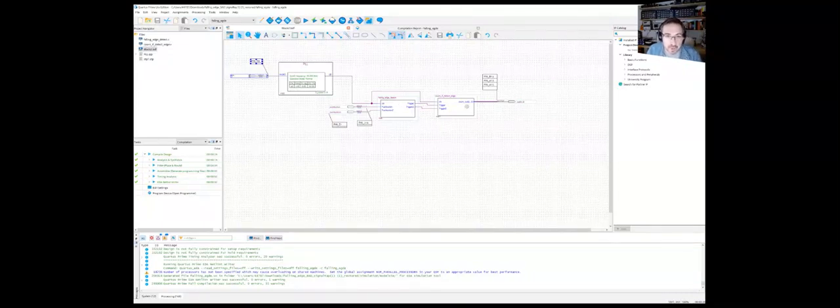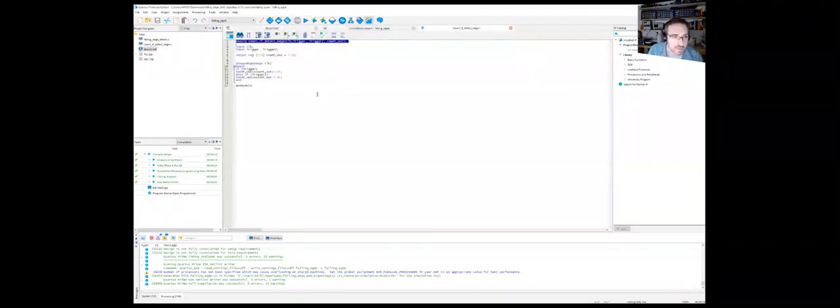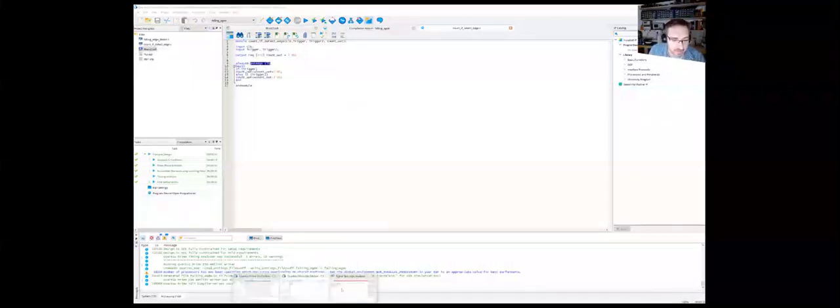And it's important because the next step in this design, as I explain in the example, is a block here which is synchronous to the clock, and it's looking for that trigger. So at the positive edge of the clock, it's looking for the trigger. If that trigger is 1, we increment the count. If trigger 2 is 1, we decrease the count. But that trigger might not be where this block expects it to be. So we're going to get unpredictable behavior.